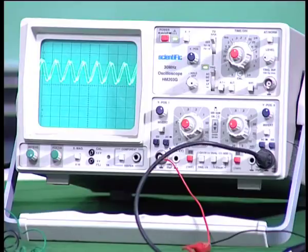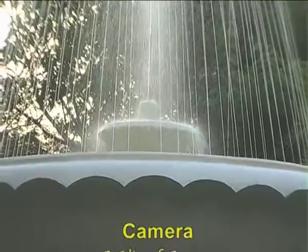So, thus we have seen in this lecture 3 different types of oscillator circuits built using op amp. One is the RC phase shift oscillator, the other one is the Wien's bridge oscillator, and the third one is the twin T network oscillator. All three are very useful, but the most useful among them will be the Wien's bridge, because it is much easier to vary the R and C components. You can have ganged resistors and ganged capacitors, and you can vary the frequency. Most of the oscillators that you get commercially in the low frequencies, less than 1 megahertz, are based mostly on the Wien's bridge oscillator. Thank you.